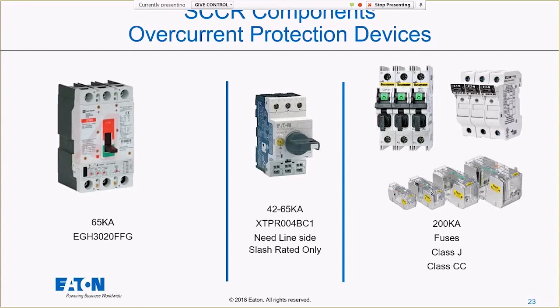If you don't need the disconnect because you don't need the isolation, you have that somewhere else, like a drive that acts as its own disconnect, whatever it might be, then you can use any old fuse holder. You can use that one that rocks out, when you don't need it to be a disconnect and you're not worried about it being misapplied.